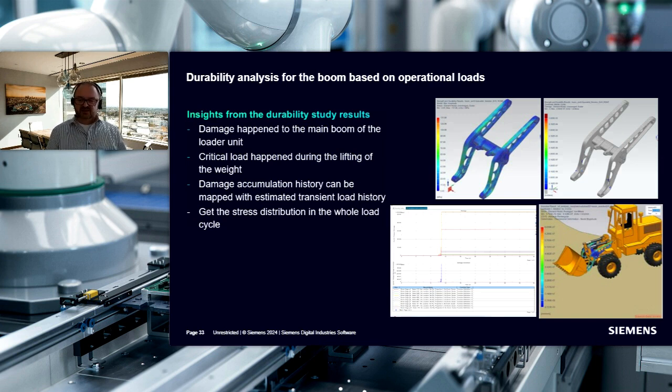But again, you now know where to instrument your structure in real life. You can create real life load scenarios. And in the second step, if you have measurement devices simple enough, you can even do this in operation, which means you really know how long your structure will still live due to the real loads which are acting on the structure. So it can also be used in the future for predictive maintenance.